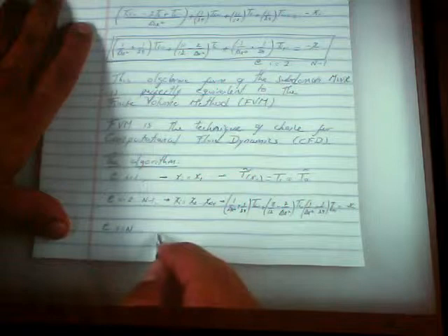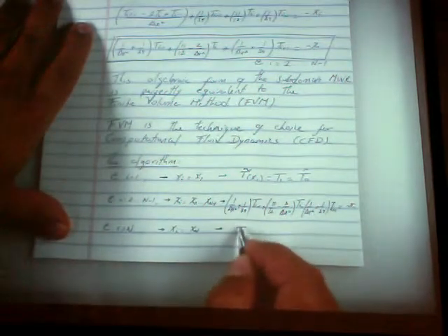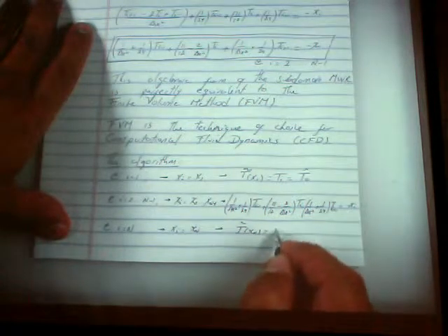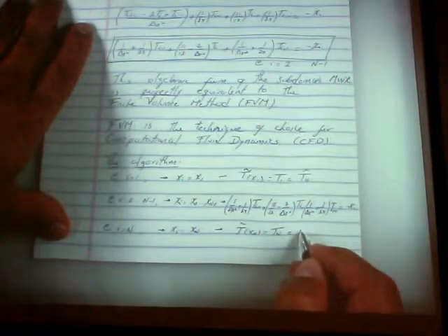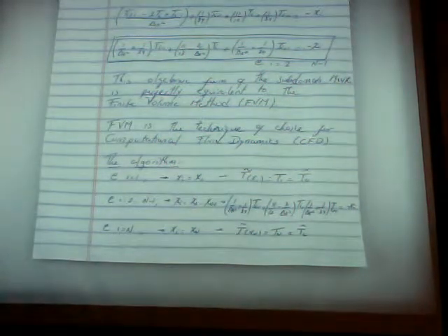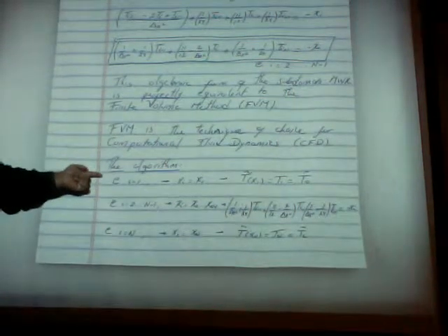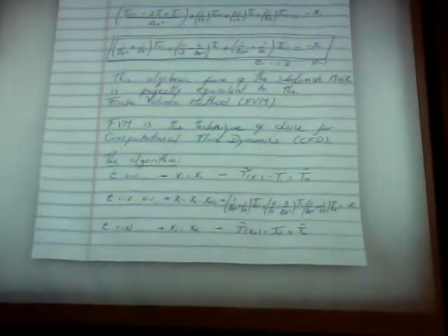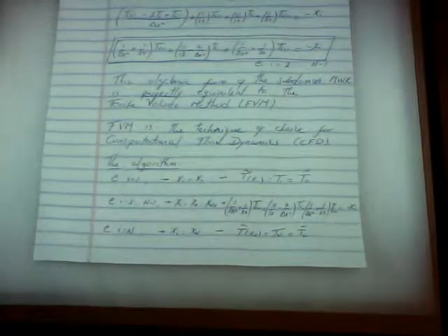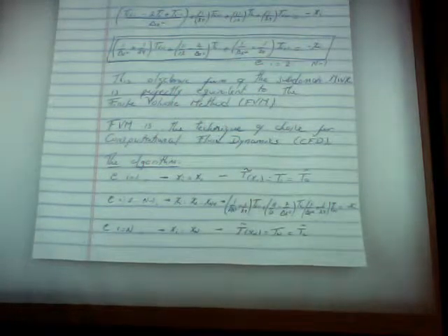And at n, in this case, again, it's simple because we have a first kind boundary condition. Again, that makes things very simple. The nth temperature is just that imposed value TL. And now we have a square matrix, right? We have n minus 2 equations here. We have equation 1, equation n. That makes up n equations for n unknowns, although the first and the last unknown are solved explicitly.